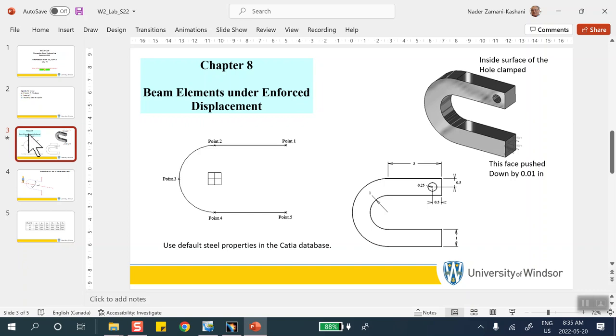Okay? And they get these stresses which are totally garbage, the deflections that are maybe garbage. So the frame, for rigidity and for deflection and things like that, should not be done with solid elements. It can be done with beam elements. Okay. Now, if you want specific information at the joint where these things are welded together, it doesn't happen at that level. But what they do is they do a frame analysis with beams. They recover the forces, and then they take that piece where the pieces are welded together, apply those forces that come from a beam analysis to that location and model it with solid elements, etc.